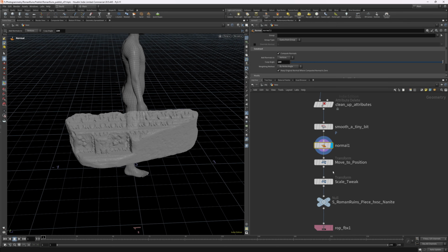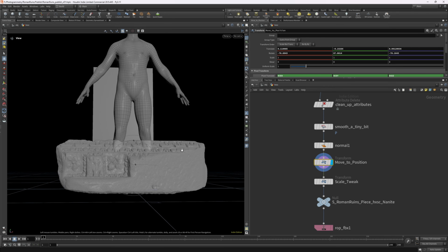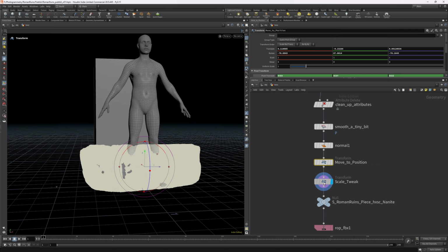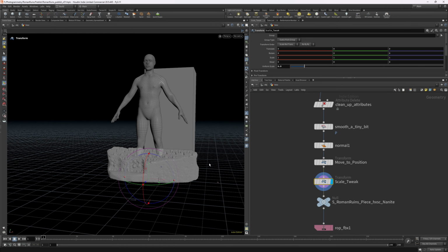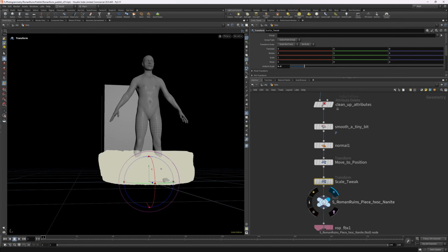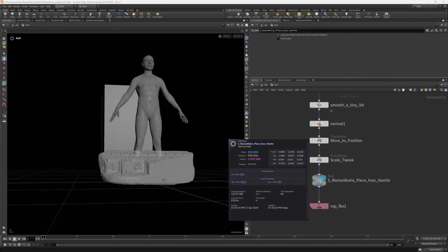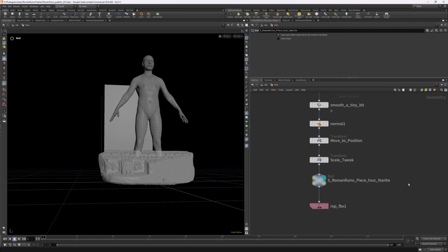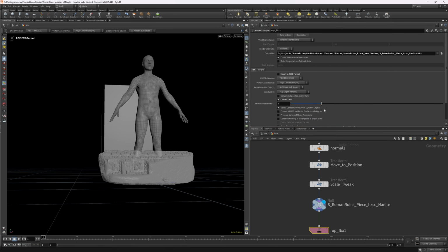And now we've got to rotate it into position. So I change that so we got it nicely resting on the ground. And I'm just going to fix the scale a little bit. It's a little bit too big, so I'm reducing it with 10%. And this node here will be the name that is in the object when you import it to other programs. So now you will have an object that's got points, normals, UVs, and it gets the name from here. So it's very, very clean and efficient. And then I just save it out to a folder in FBX.